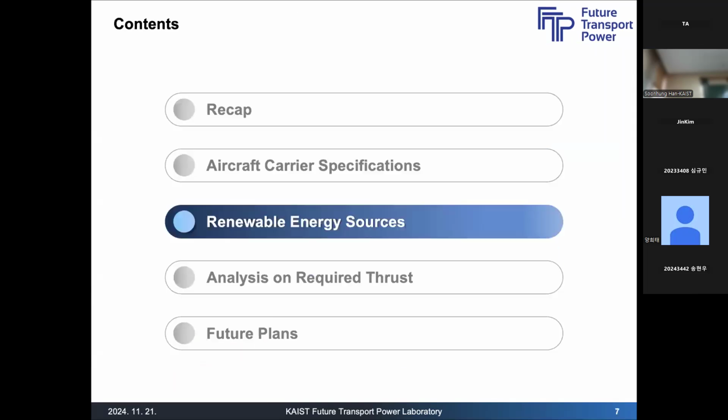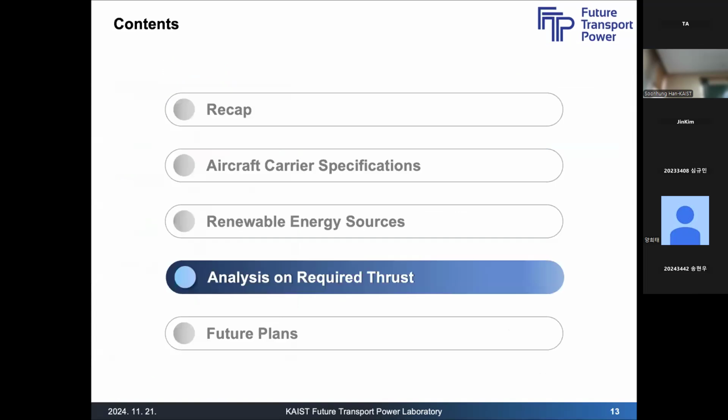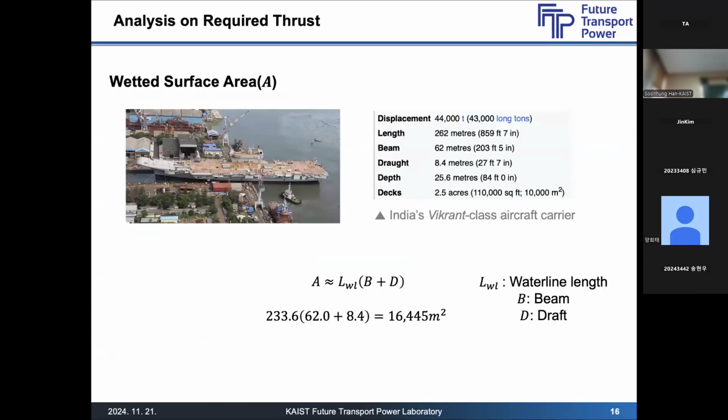So you may try to interpolate using that engine size. That may be a simpler, quicker estimation of power. Because your ship and the Indian ship are similar, you said, but a little bit different, right? So you may adjust the number. You may have two tracks, from the resistance or something like that, but from the top, the engine size of the Indian ship can be worked down.